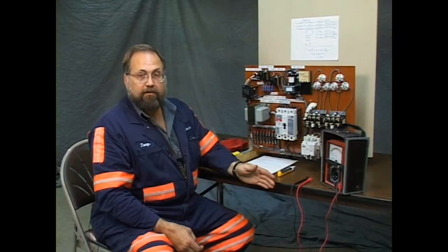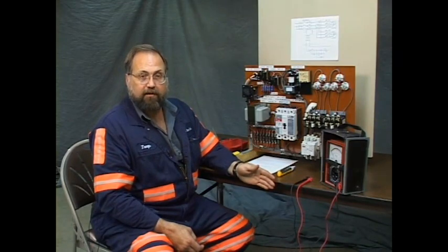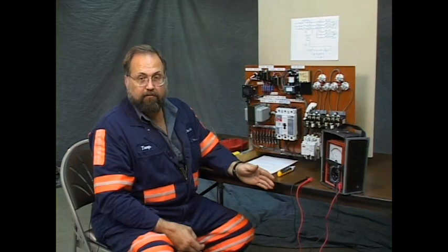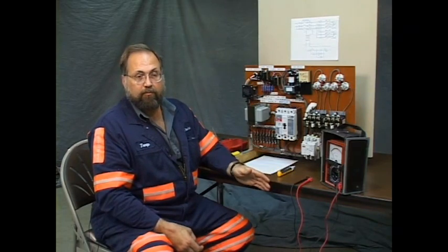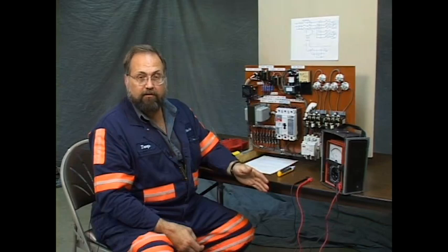If the start switch was in a snapped closed position, as soon as the overload cooled and reset, the motor would start again. And without an operator depressing a switch, you wouldn't know when it were going to start. It would just start when it became ready to start. That's undesirable on a piece of equipment.